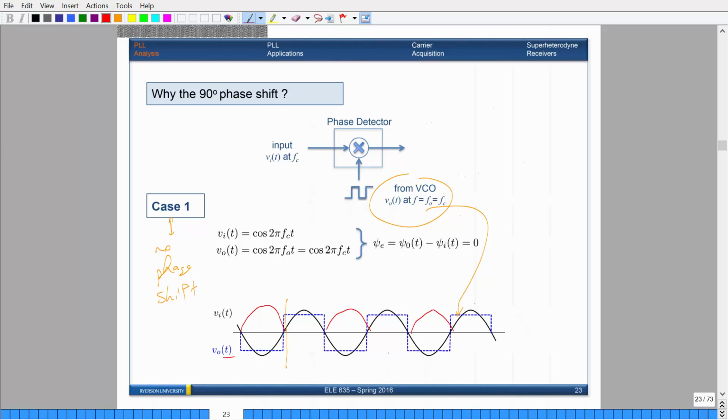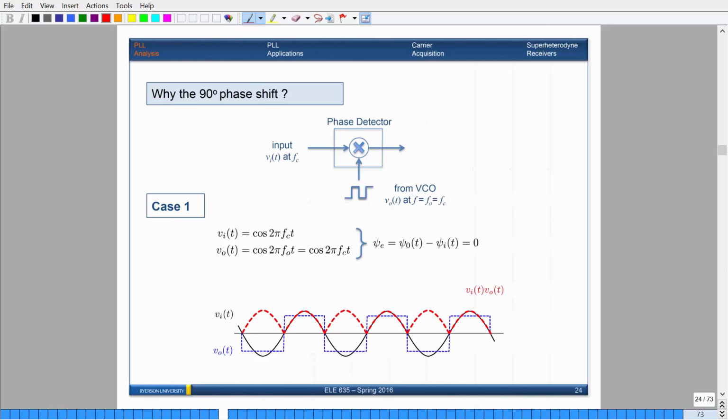Remember, the square wave fluctuates between -1 and 1. So for your cosinusoid term, if you take each of those negative numbers and multiply them by -1, you're just flipping it, so that it goes to the top. So what's happening here is you are performing a rectification, where any negative values become positive. And that's what's happening here.